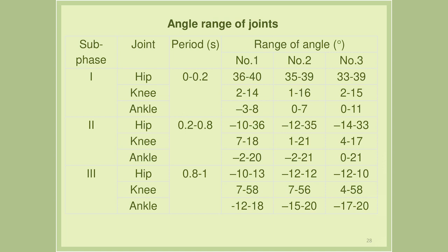The natural gait would be roughly divided into the support phase and the swing phase. Compared with the swing phase, the support phase is more complex. According to the ground reaction force measured by the foot force plate, the support phase is divided into three sub-phases further. During sub-phase 1, the heel of the swing leg strikes the ground and the two legs support on the ground at the same time initially, during which process the center of gravity transfers from the later leg to the front leg gradually.